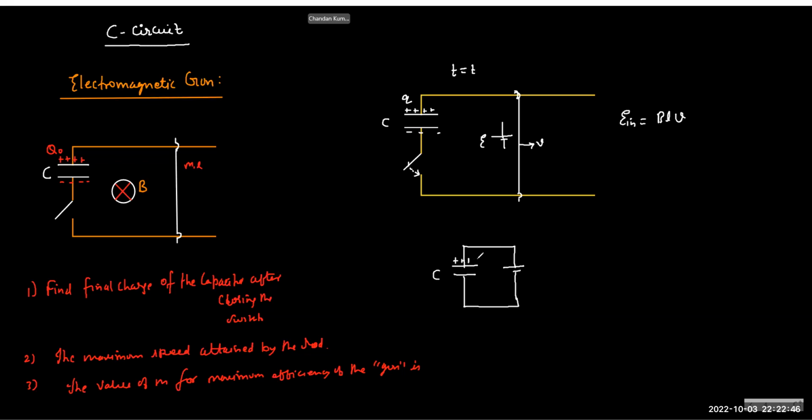And we know this is Q. What will be the relationship between these two? Also remember that in the beginning, the charge is creating a current this way. It is not the battery which will decide, it is the capacitor, because the capacitor has high voltage in the beginning. So current will flow like this.